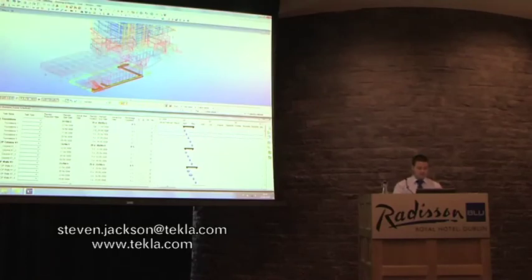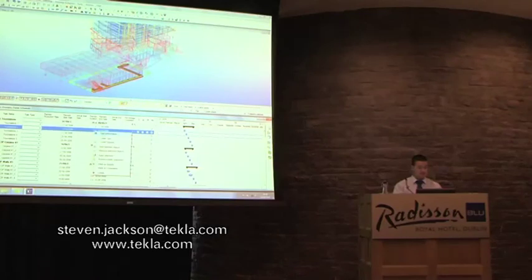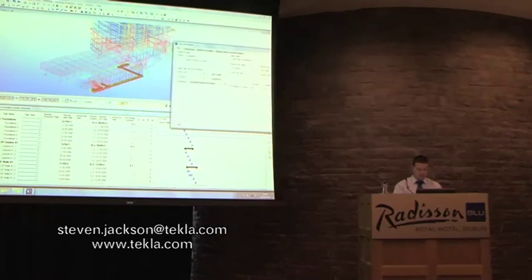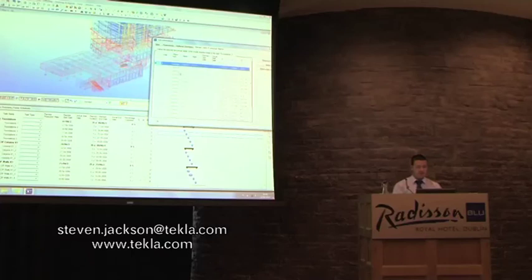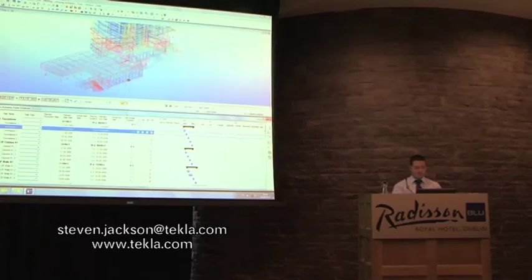So we can get the information for a 5-day task that's in there. And all these parts that you see in there are stored. We can set the task type, for formwork, for pouring, for erection and things. But what we have in here as well is all the parts. Each individual part is stored in here, so we can control the erection sequencing of these things. And of course we've got all the dates down here that we can plan and control.